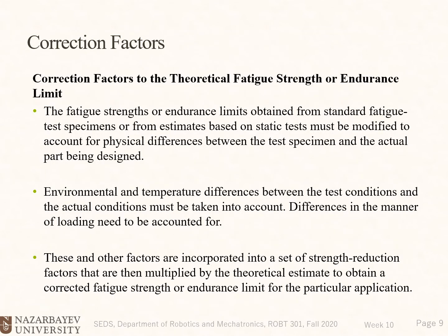Now we should see what correction factors are and how we could apply them to the theoretical fatigue strengths or endurance limit. The fatigue strengths or endurance limits obtained from standard fatigue test specimens, experimental data, or estimates based on static tests must be modified to account for physical differences between the test specimen and the actual part being designed.